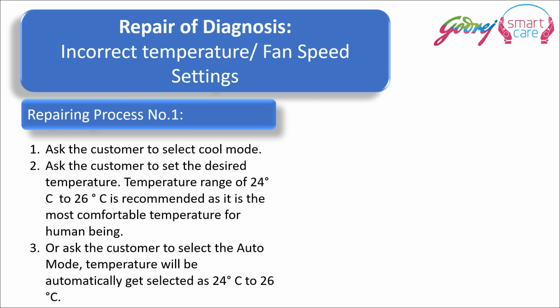A temperature range of 24 degrees centigrade to 26 degrees centigrade is recommended as it is the most comfortable temperature for human beings. Or ask the customer to select the auto mode. The temperature will automatically be selected as 24 degrees centigrade to 26 degrees centigrade.